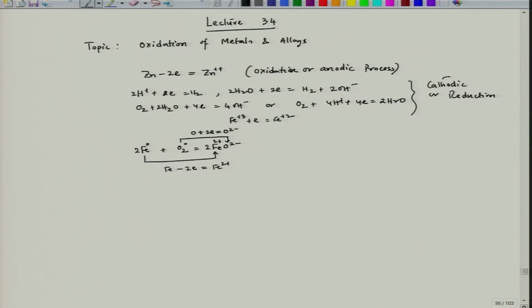So, here also, in case of corrosion, this entire process we are talking about is from a corrosion perspective, where zinc dissolution happens at room and ambient temperature in HCl medium, where I can have oxygen present as dissolved oxygen, or I can have ferric ion in the form of impurity, and then this could be your anodic process, and all those reactions can happen depending on the pH of the solution.